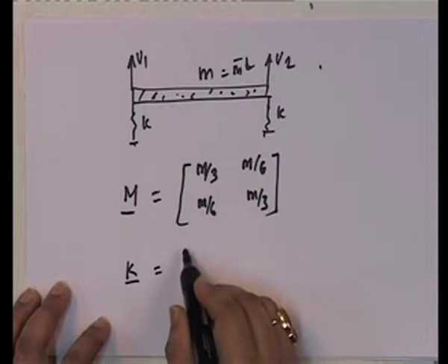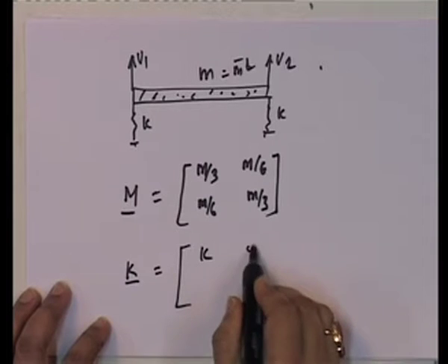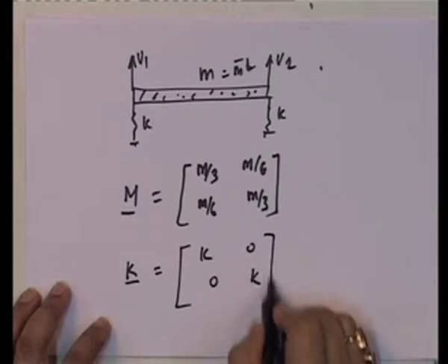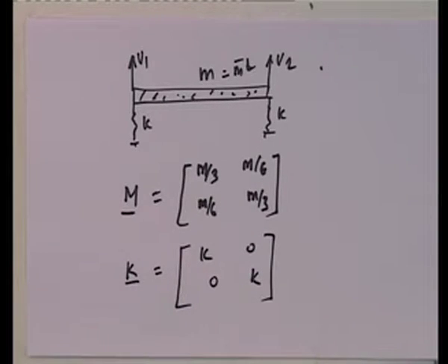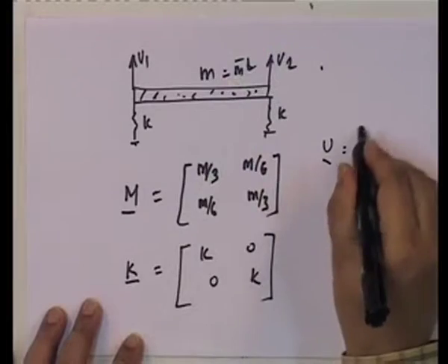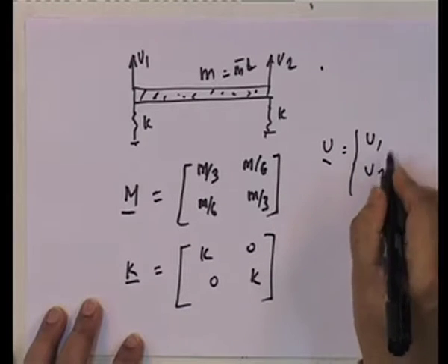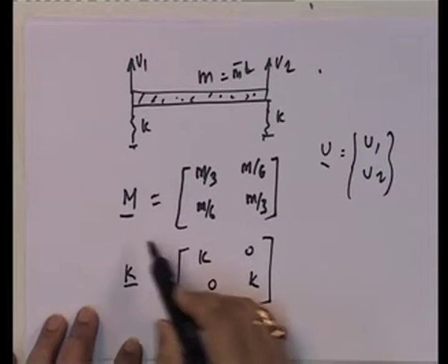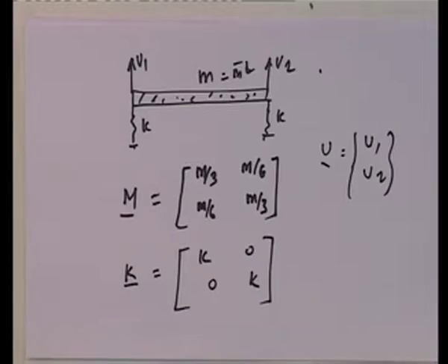The k vector you will see just like the way we evaluated it is this. Okay. So, now corresponding to V, these are the mass and stiffness matrix. They look completely different from the mass and stiffness matrix corresponding to the degrees of freedom Vx and V theta defined at the geometric center, completely different.